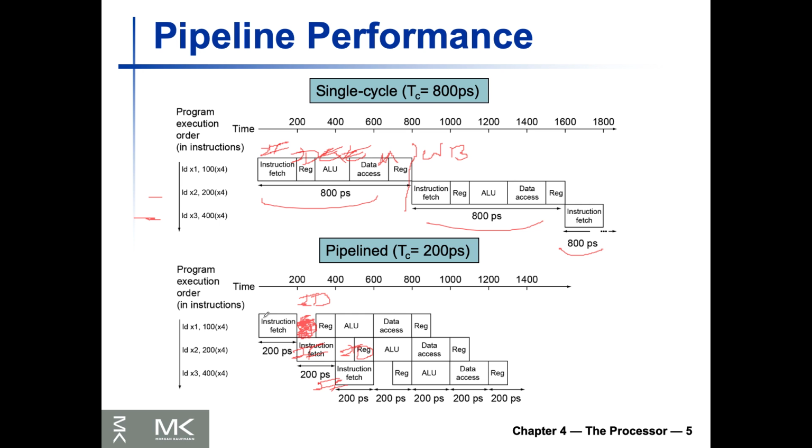So you add them, now you have to look at them this way, from here up to the point they're finished, okay? And that's going to be the overall pipeline up to this point. But each of those only takes 200 because you have to take the highest amount, the slowest stage that would take to run, which is among 100 and 200, it would be 200. So the rest should wait that 100 to match the cycles. If all the cycles had the same amount of time, all of them would be equal.